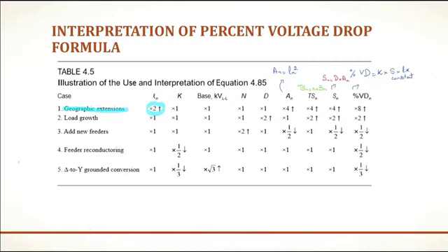So if we double the length of the feeder, we know that K is not going to be changed because that is independent of the length. Definitely voltage will also not change. We are not changing the number of feeders, so this is not going to be changed.